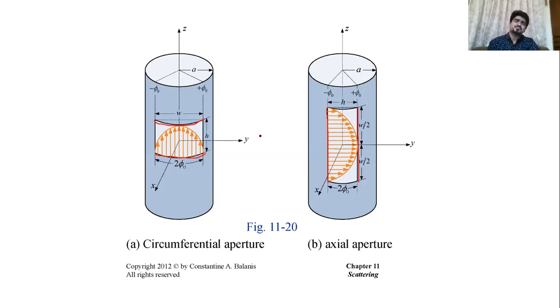Now if you look at the field distribution, you can explain it from the field distribution of the dominant mode for the rectangular waveguide. If you remember, for the rectangular waveguide, for TE10 mode, we had similar field distributions, right? Since this is an aperture having a rectangular shape, it will have a similar field distribution, since it has PEC edges on the four walls. We have gone through this in chapter 8, so this should be obvious to you.